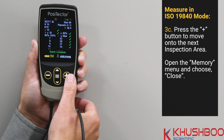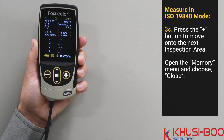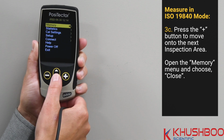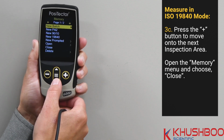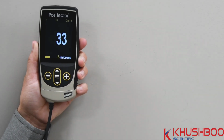Once the required readings for the first inspection area are taken, the user can press the plus button to create a duplicate ISO 19840 batch or close the batch by going into the Memory menu and selecting Close. If new specifications are required, a new 19840 batch will need to be created.